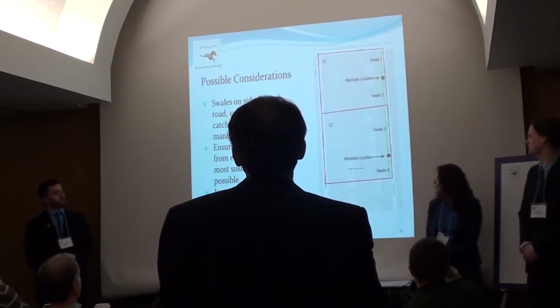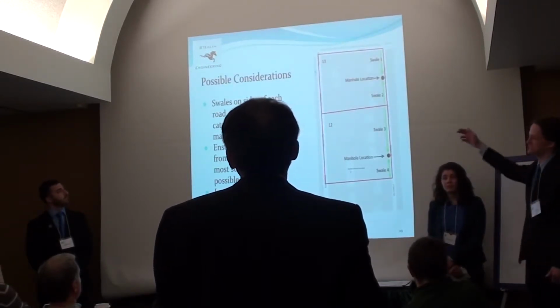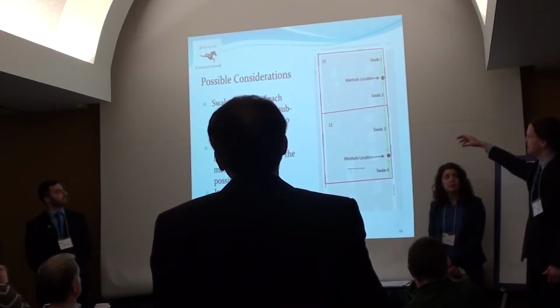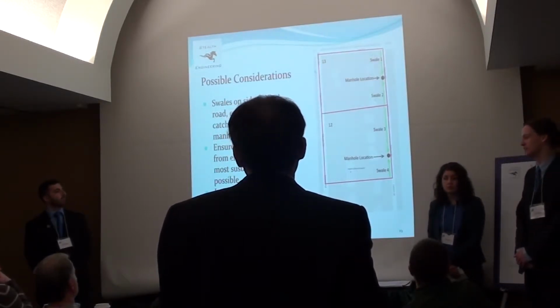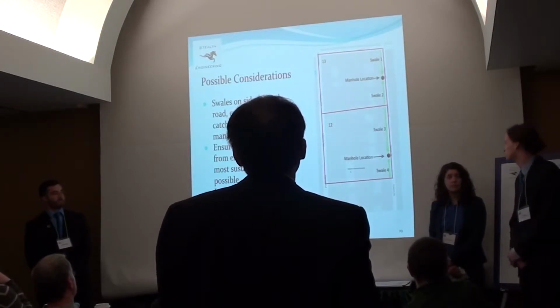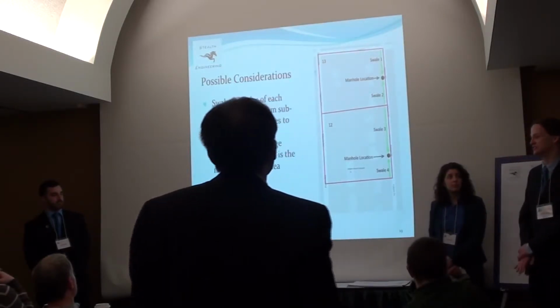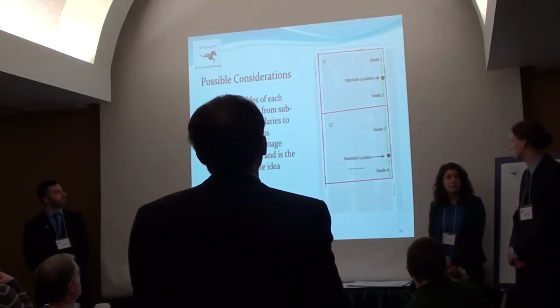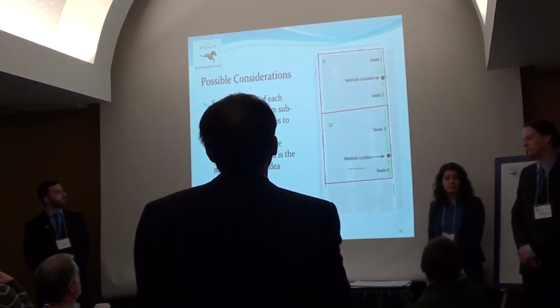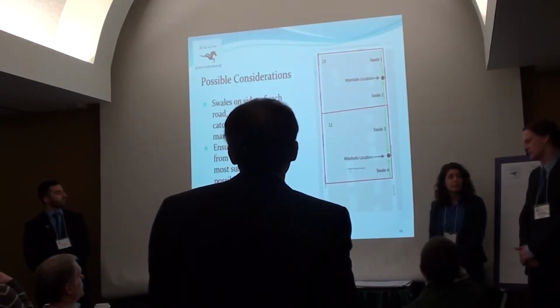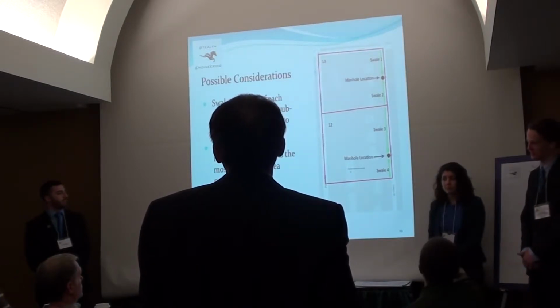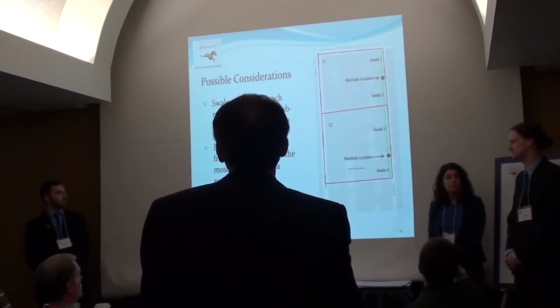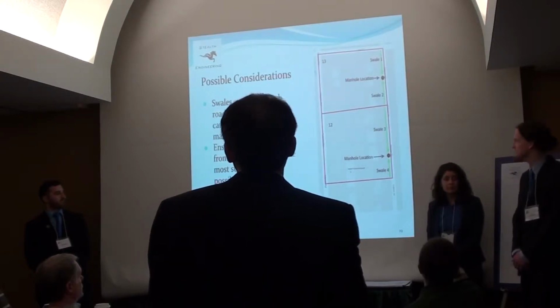For a sustainable idea, we proposed that there could be swales on either side of each manhole, extending from the manhole to the boundary of the sub-catchment area, leaning in towards the manhole such that all the runoff will be directed towards each manhole. The issues involved with this are acceptance from the public, as they might not enjoy swales throughout the whole neighborhood in front of all of their houses, and possibly safety issues with ditches in front of houses.